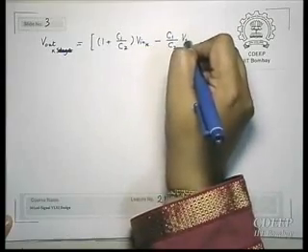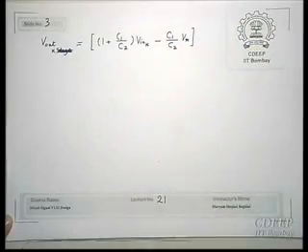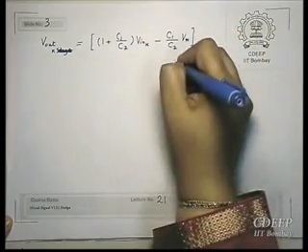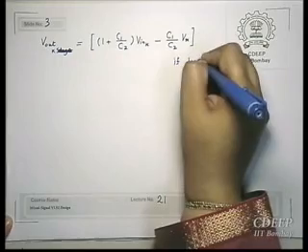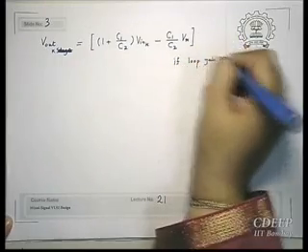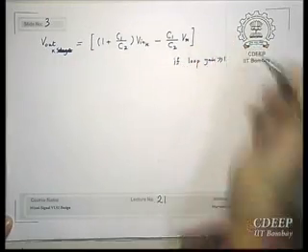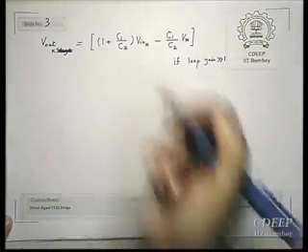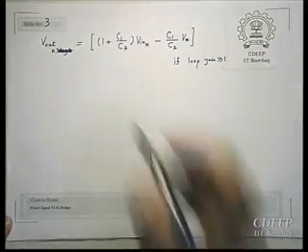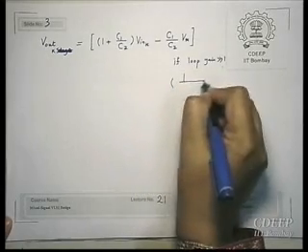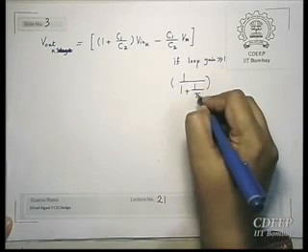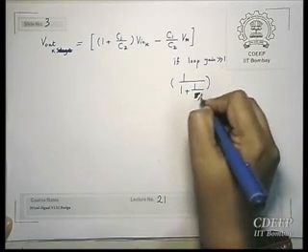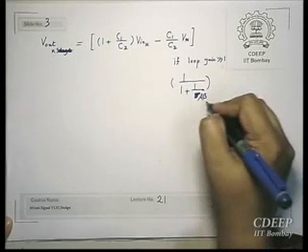This is what is written in the paper. Of course, we are talking about the bandwidth of the Opamp. If the bandwidth of the Opamp is very large, the loop gain is very large, then you can have this output almost this. If the loop gain is not very large, you will get this term. I use the notations which are used in the paper, it's better.